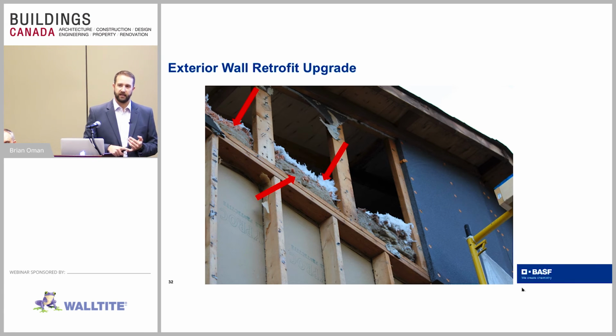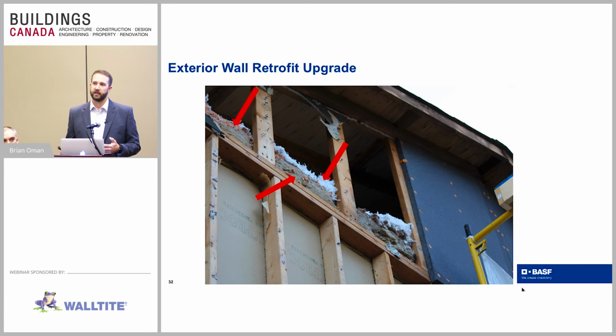Again, we can correct any structural issues, ventilation issues, or electrical issues that are going on in that attic space. We can put a proper air and vapor barrier down to improve the performance of the attic portion of this assembly, and then utilize a properly installed blown-in or batt insulation on top of it to ensure that we know truly what our attic insulation assembly is like.